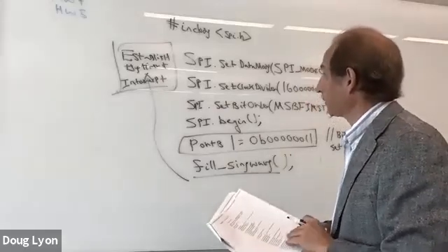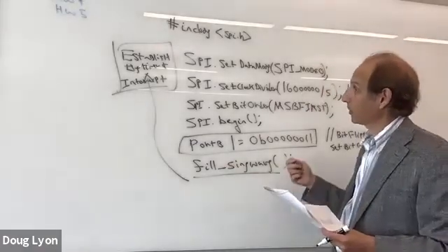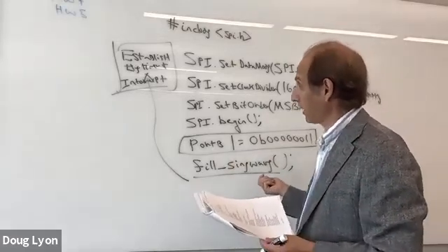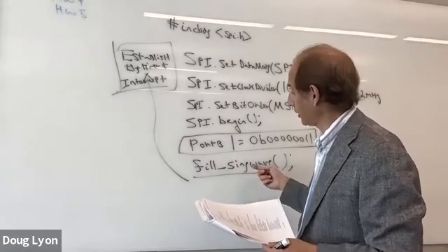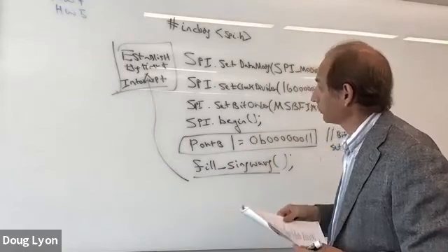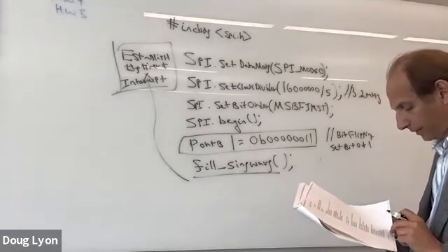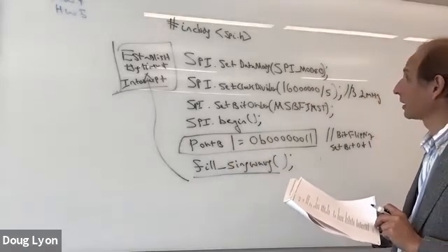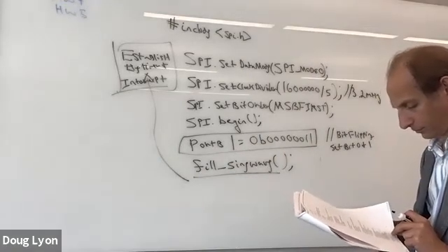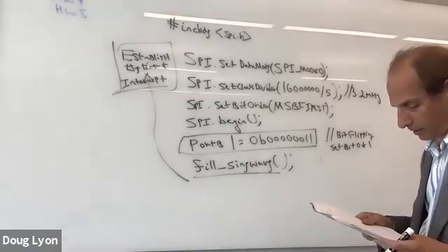So when you have interrupt-driven processing, what you expect is that the Arduino is going to be busy doing a lot of other things, because we know there's like a 100 to 1 or even a 1000 to 1 ratio between the Arduino clock and the sample rate. And so what we'd like to do is we'd like to let the Arduino do something else in between samples. So we'll set up a clock to trigger an interrupt that causes us to pump out more data to our DAC. And there's a little detail there, which I'm not going to go into right now.